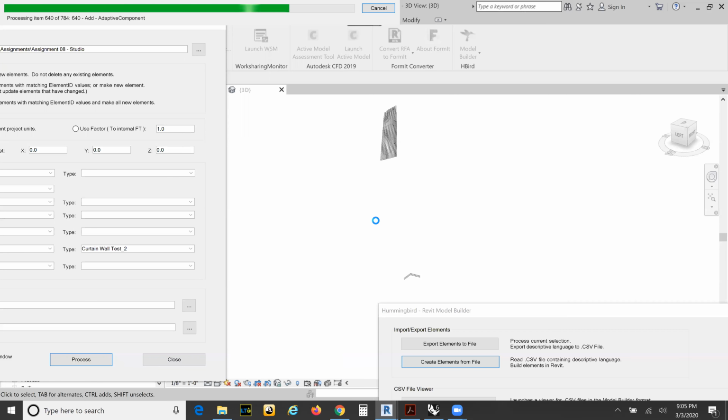Since it might be so few of them, you can just physically move it, or you can isolate those 4 in the list and just reverse the order, which is more Grasshopper. It's dealing with a lot of the data tree. It depends on how often you're going to be doing this. If you're going to be recreating this over and over again, it's really important to probably do that in Grasshopper, so it'll always be fixed. If you're only doing this once or twice, I wouldn't worry about it. You fix it manually.